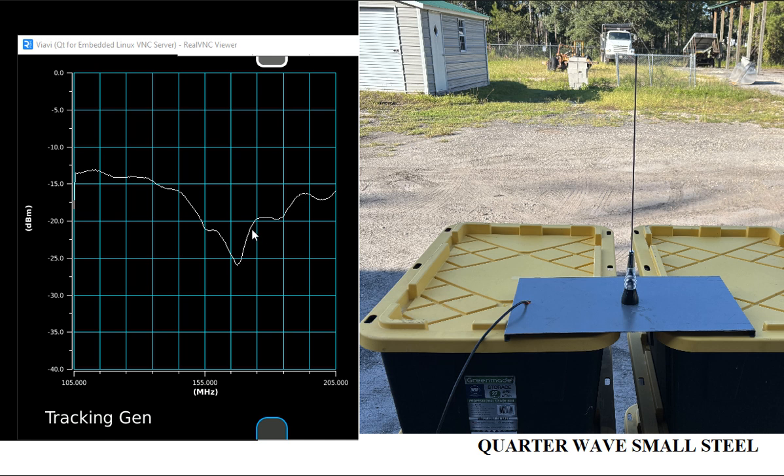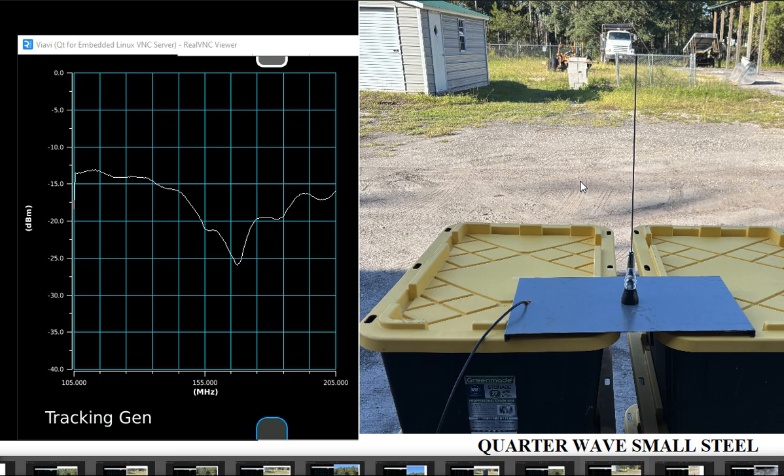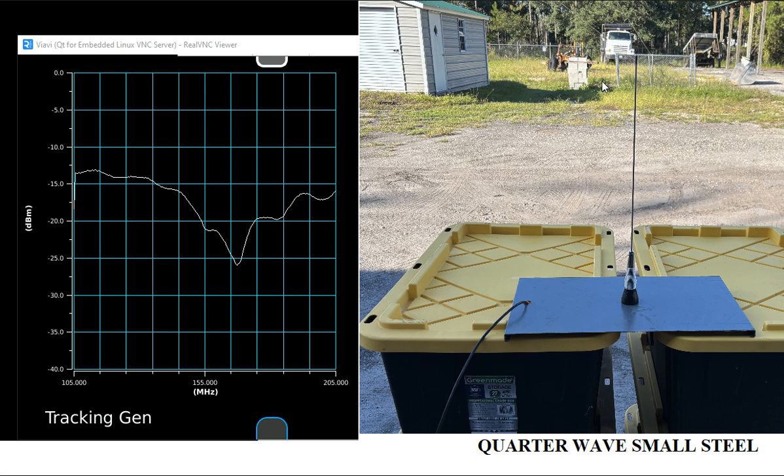And I just wanted to show you guys a really quick trick to just confirm your sanity and make sure that that's what it is and that you're going to be able to do the right amount of length. And that's just taking a piece of solder, a couple loops of solder, and wrapping it around the top of the antenna and having a little bit poke up the top to give you virtually a taller antenna.